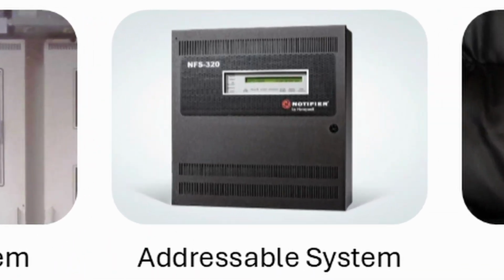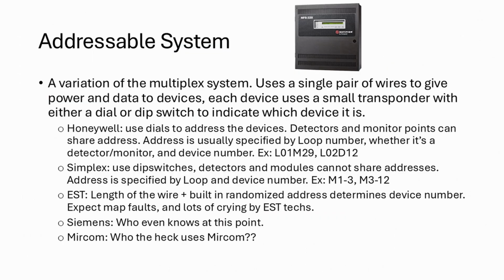Addressable system. Addressable systems are a type of multiplex fire alarm system. They use a single pair of wires to give power and data to each device, such as pull stations and smoke detectors. Each of these devices have a small transponder inside of them, either using a dial or a dip switch to indicate the device it is.